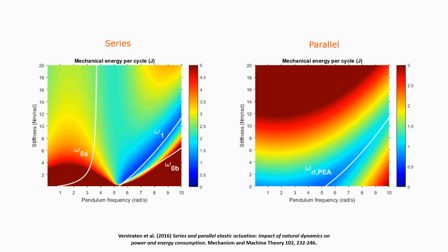Is it the series or the parallel topology? There are many different opinions among researchers, which sometimes lead to intense debates, but general guidelines simply do not exist. In search for answers, I studied both actuators on a simple setup, the pendulum that you saw previously in the video. In simulations and experiments, I looked at both the mechanical and electrical energy consumption of the actuators for a wide range of stiffnesses and oscillation frequencies.